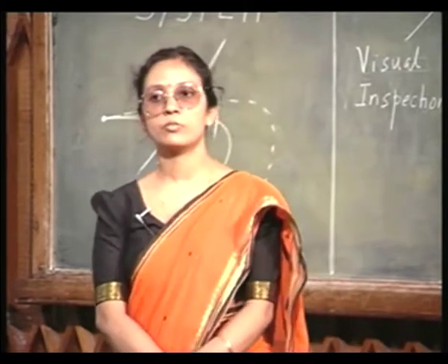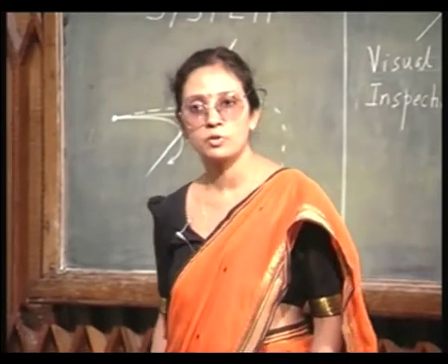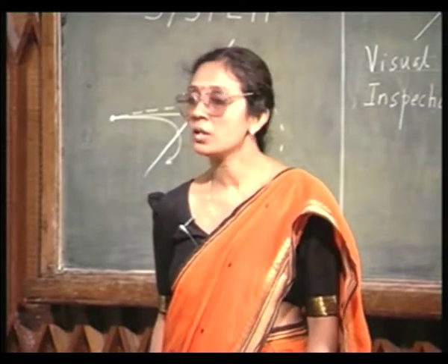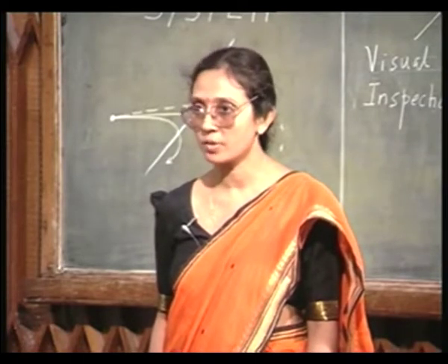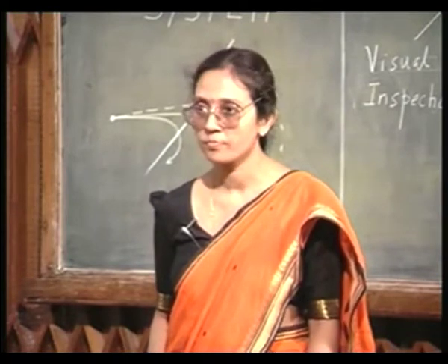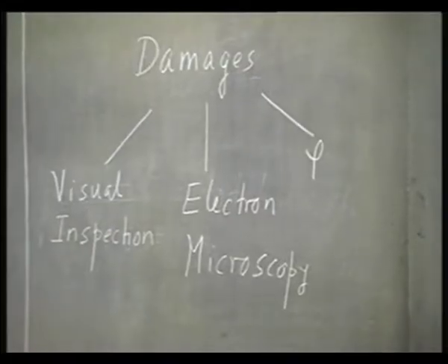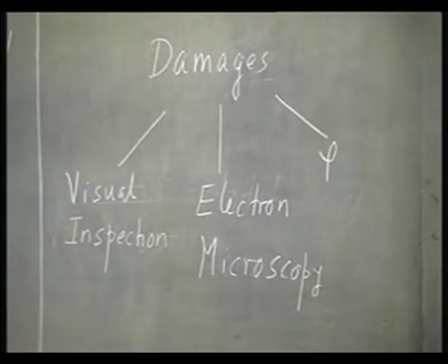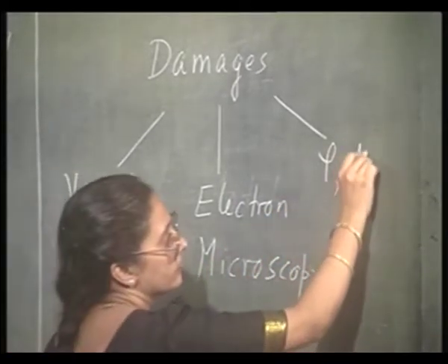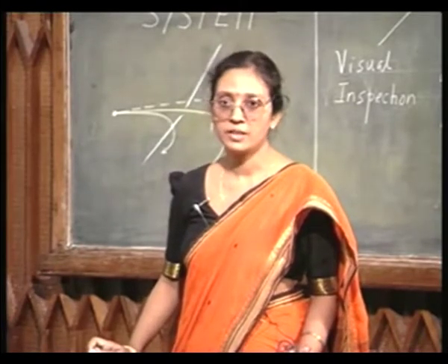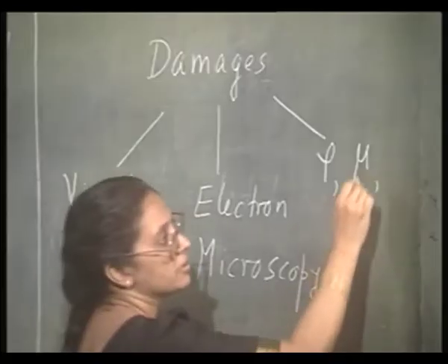What are these factors? First of all, for an electronic engineer, the most important idea is the conductivity, right. In a damaged surface, the conductivity is going to be extremely low. You are going to have a highly resistive surface because of the damages. The electronic activity will be extremely low. So, change in conductivity, and then in a damaged surface the mobility is also going to be extremely low. So, mobility is the second casualty, and finally the lifetime, that is the third casualty.